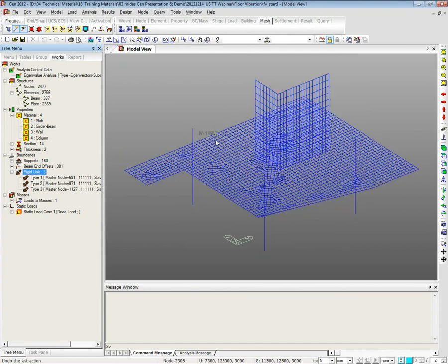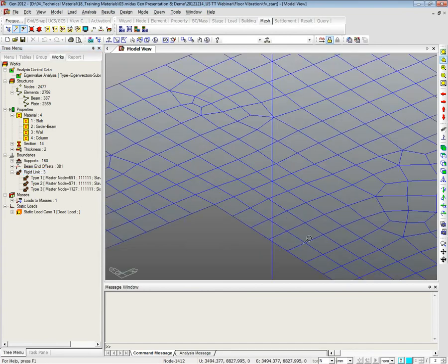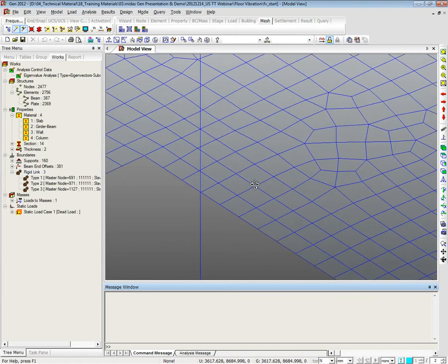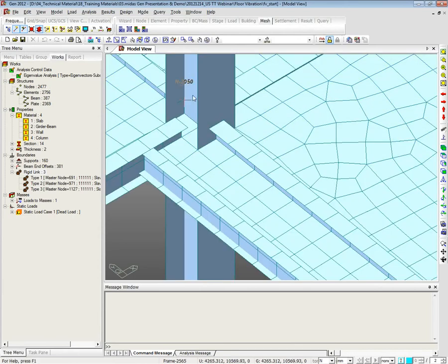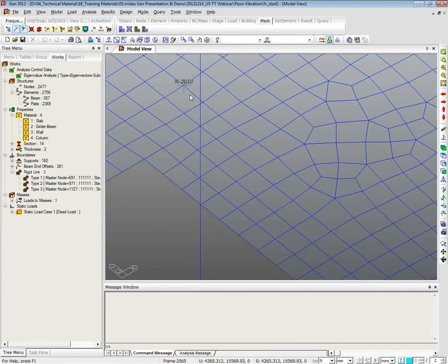For the joint between the columns, for example, this node is continued for the columns and plate, but it is concentrated to one node too much. And it is different from the realistic state because our FEM model cannot consider the area of the column. So we used the rigid link.